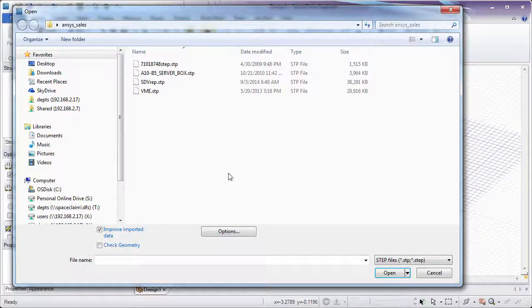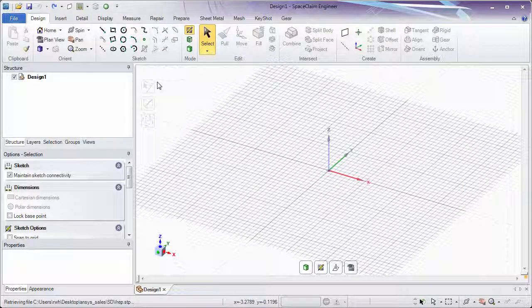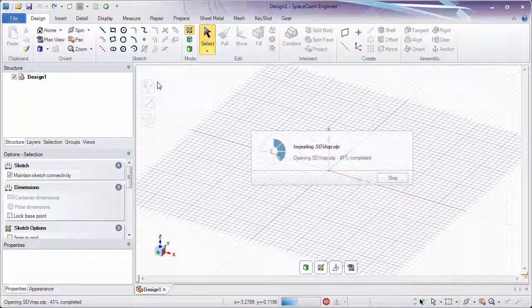In this demo of the week, we're going to be looking at creating an outer air enclosure on a model. One of the things we're going to focus on is fixing some of the imperfections in a model that can get in the way of creating a nice, robust outer air enclosure around a model. Two things we're going to focus on specifically are repairing a model to get a robust solid, and also removing any internal geometries which might get in the way of creating that outer air enclosure around the part.